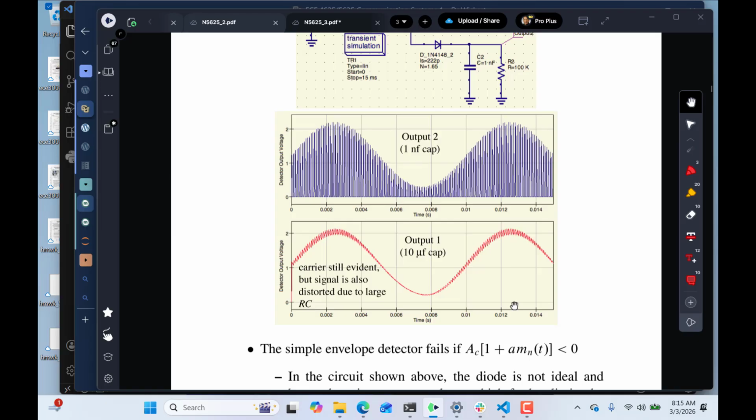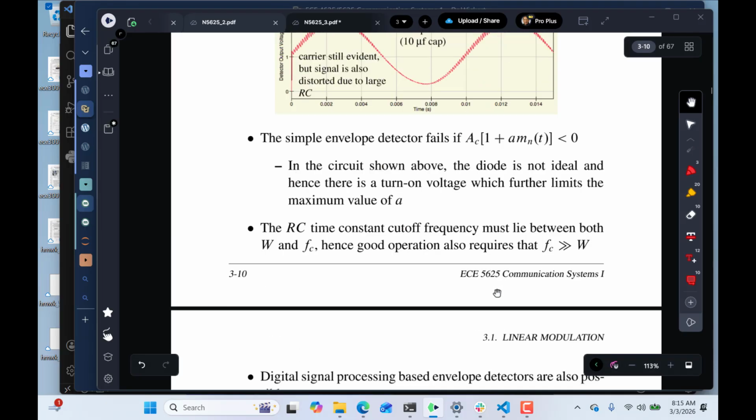Not for AM radio so much as just sensing the power of a waveform. You can filter away the carrier cycles pretty easily the higher the frequency is, because the first order low pass can roll off over many decades if the carrier frequency is high.